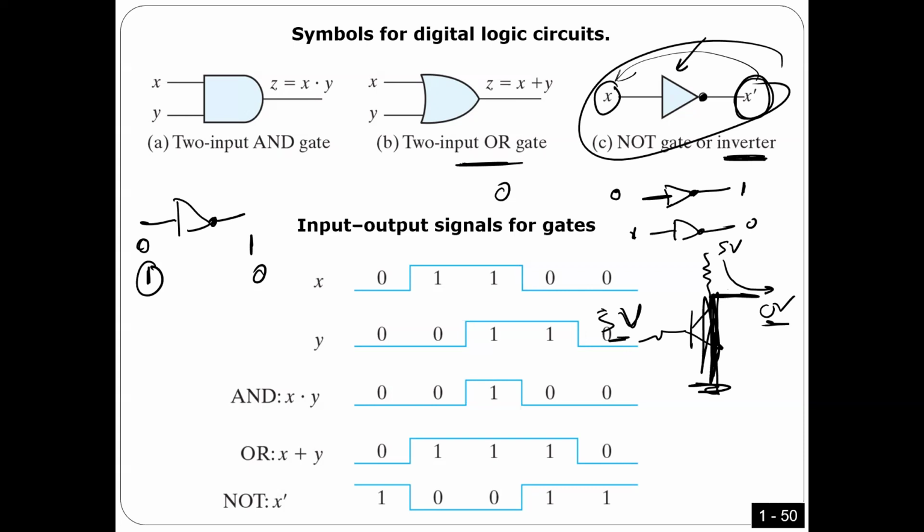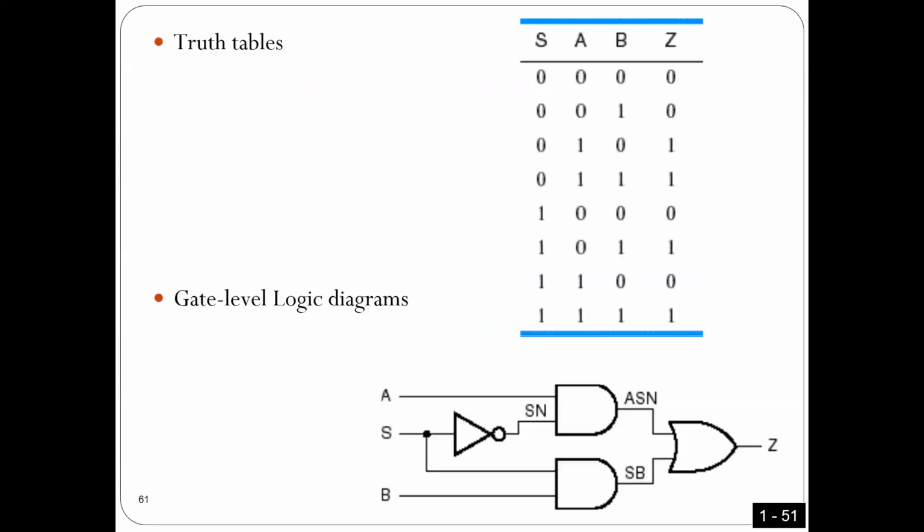Okay, one more thing you should understand. In the case of the inverter, I have logic 0 and logic 1. This is the logic. Every logic level has an equivalent voltage when you talk about the implementation or electronics. Usually, logic 0 is equivalent to 0 volt, and logic 1 is equivalent to 5 volt, and that's what you will see in the coming lab.